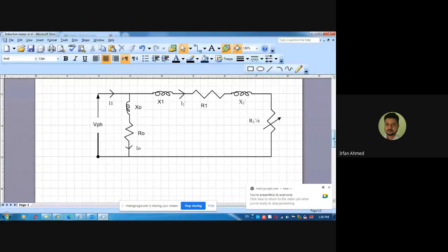Okay. So we have finished the speed torque characteristics of DC motors, shunt as well as series, under motoring as well as braking conditions. We already know that the DC motor is the preferred motor, or at least was the preferred motor for variable speed drive applications. However, now, because of power electronic converters, it is now possible to control the speed of induction motors also easily, because of which they are also gaining popularity in variable speed drives.